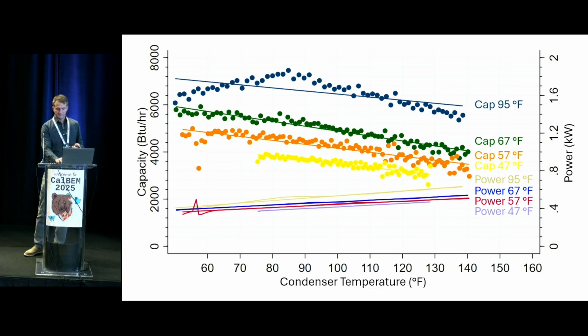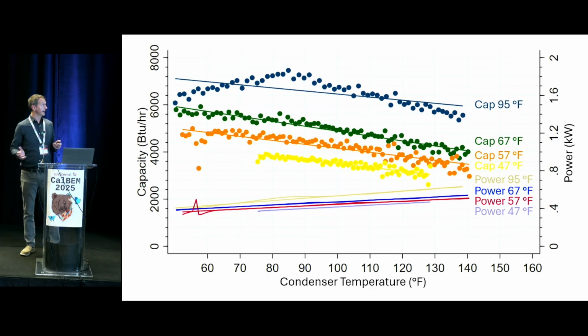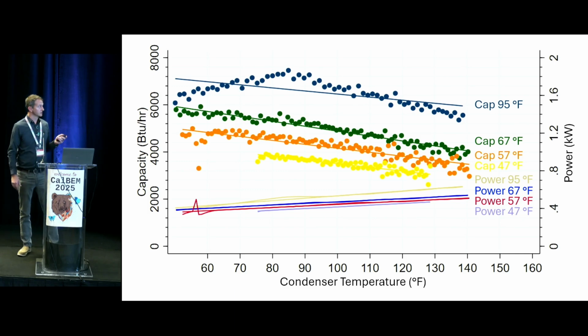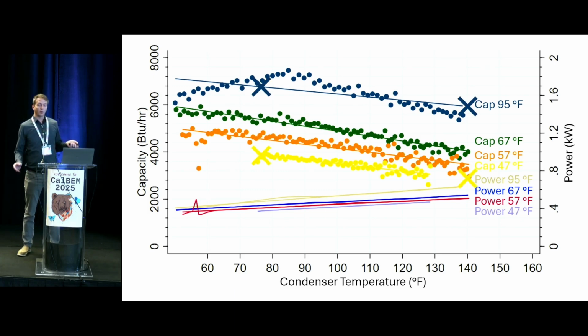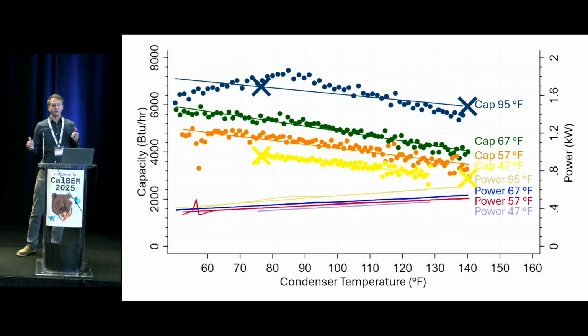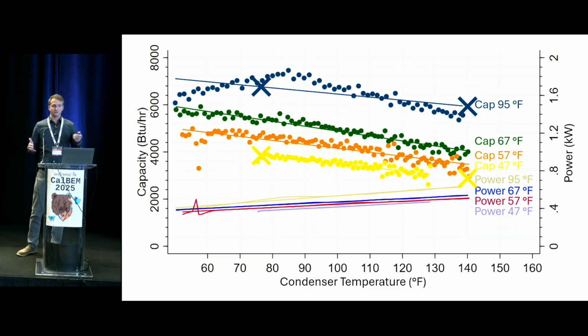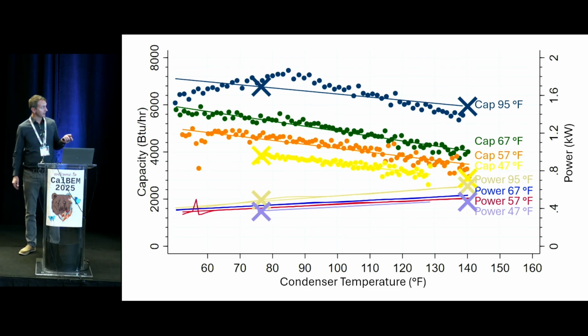All right. So historically, in energy modeling, we would just look at this and try to fit a biquadratic curve with 10 decimals of precision and call it good. But I would argue that for something like this, we can probably characterize both of these with just 4 simple points. It's fairly linear, and any non-linearities in there might be artifacts of the data, and there's just a lot of noise relative to the accuracy that we need. We're going to do the same thing for power. It's mostly linear, so we only really need 4 points to characterize it.